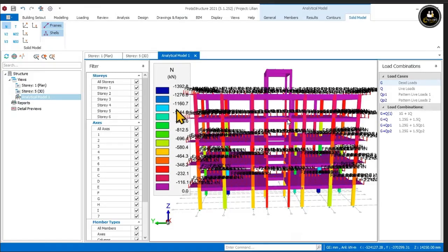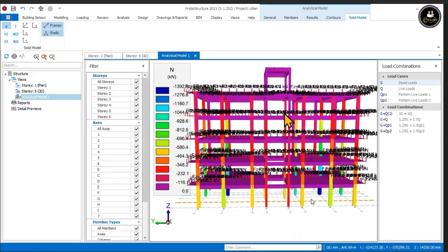Okay, 12 was okay, but let's go back to... we had also the live load of terrace level because it will act like a terrace in one aspect. That's where people will be, if from the architectural drawing it was named as a terrace level. Oh, okay. Now I understand. So that's why I had used a live load of 5, because I think you recall suggests we use 5. In fact, it's inbuilt in the library. I was just seeing at this model, and I'm just noticing why are our slabs so much strained? Strange, yes, but it's okay.